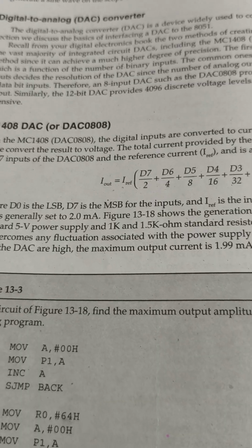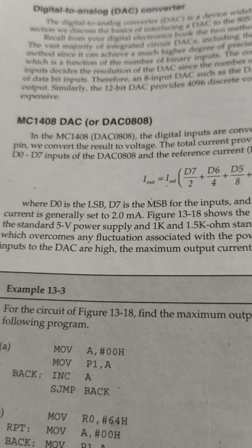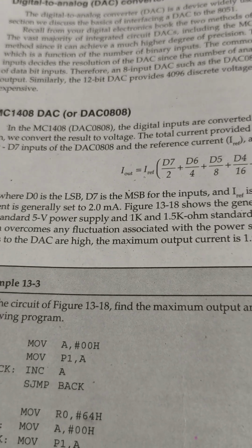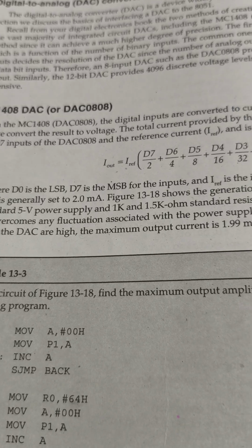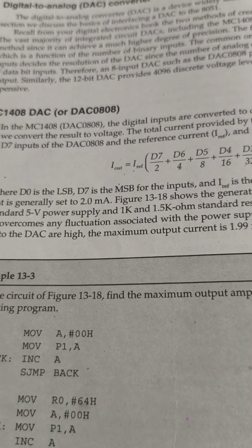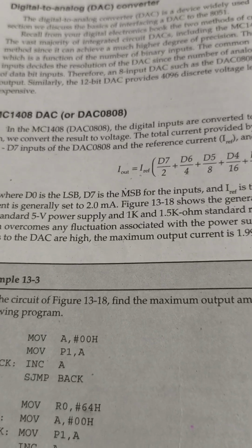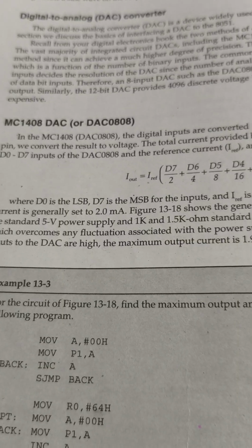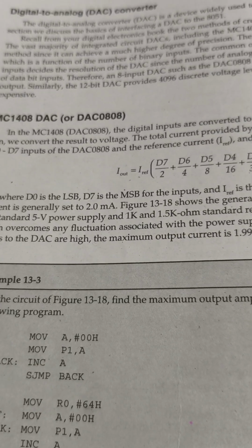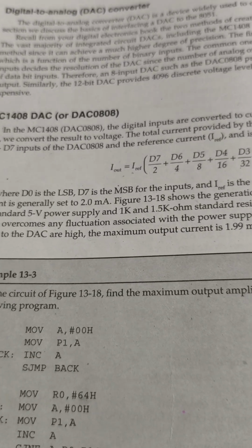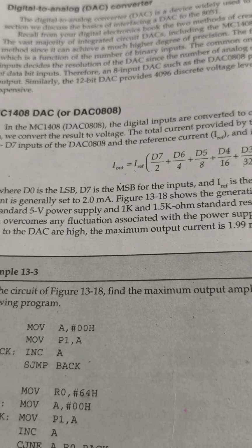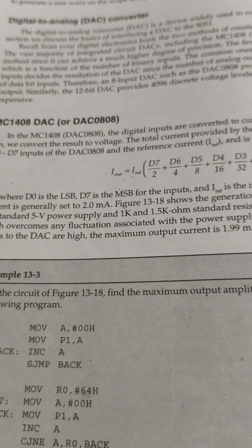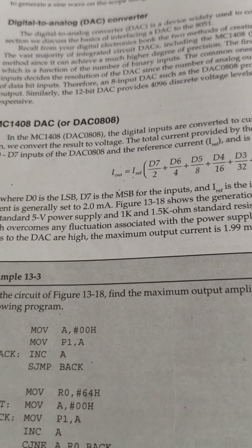We did that in MTech. We used an embedded based PWM inverter to drive the induction motor, with speed control by varying the duty cycle. In that we used the Atmel 89C51 microcontroller. Using that we can control the speed of the induction motor and also protect the induction motor.